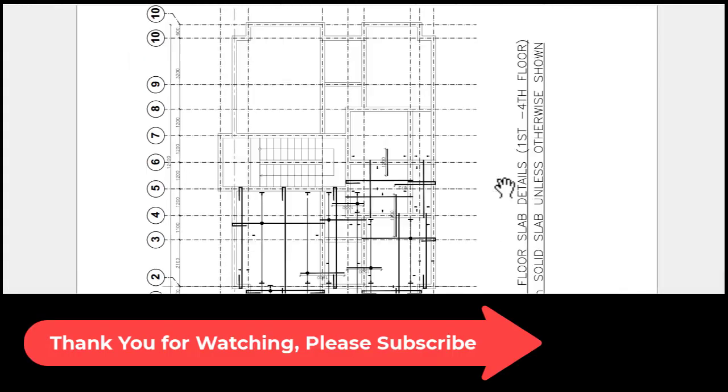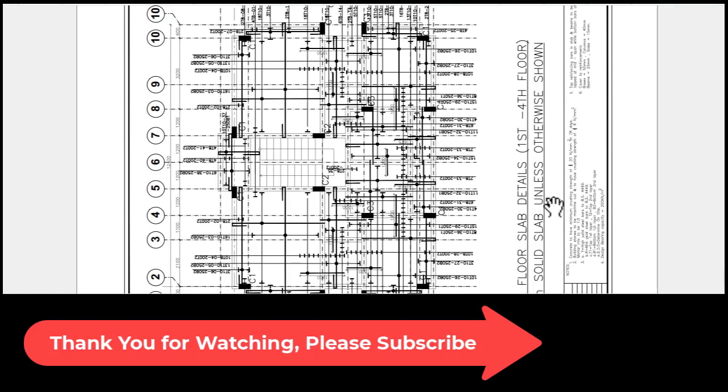But then when you read here to the detail, you can see very well that it's shown typical floor slab details from first to fourth floor. Okay, 150 millimeters solid slab unless otherwise shown. Okay, so yeah, that is for the first floor to the fourth floor. Okay, so we can get to the plan, we can get to the sections where it's been shown.